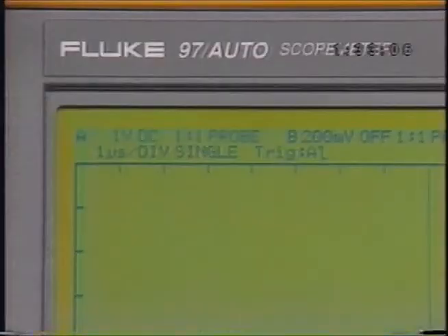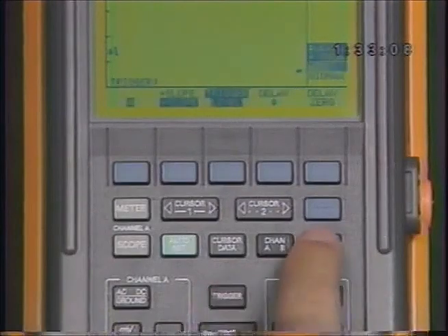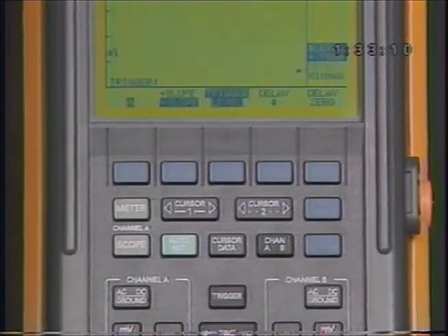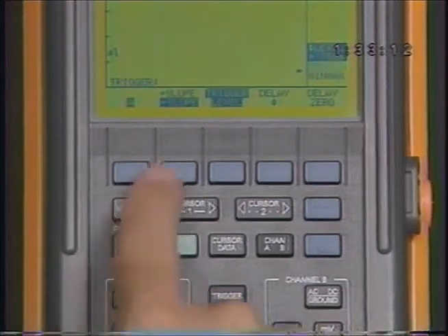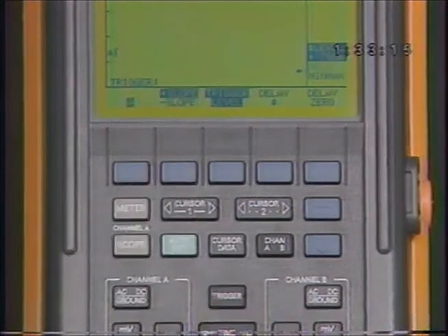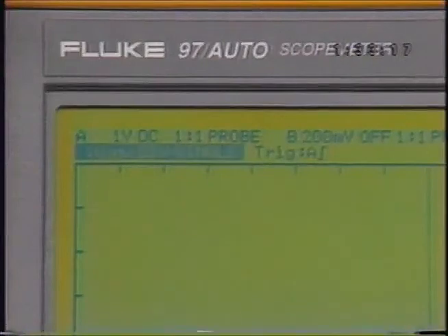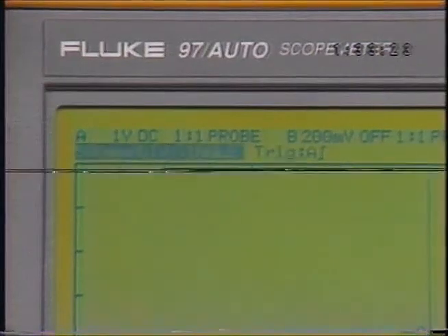Set the trigger level to about 100 millivolts above the minimum voltage level you recorded earlier, with a positive slope. That keeps the trace from starting until you begin the voltage sweep. Adjust the time base to about 500 milliseconds per division, and set the trigger delay to begin its trace at -1 division.